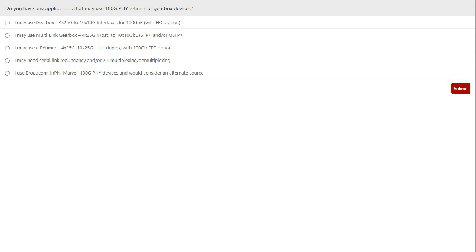Another one says I may use retimer 4x25 gig, 10x25 gig full duplex with 100 gigabit FEC option. And another answer says I may need serial link redundancy and/or 2:1 multiplexing, demultiplexing. And our final answer that you can select: I use Broadcom, Inphi, Marvell 100 gig PHY devices and would consider an alternate source.